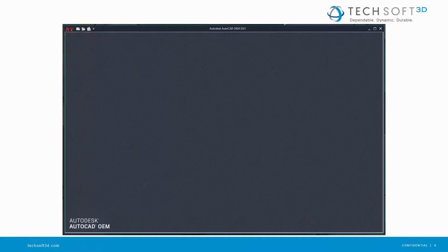This is in combination with startup 2 or 3. Otherwise, you'll get an empty drawing or open drawing dialog box. Notice that in this exercise, we're relying on the ribbon being initialized. Thus, startup value needs to be 3, which is the default value.